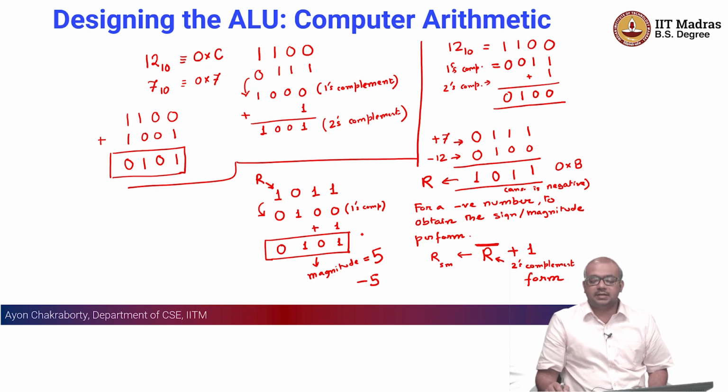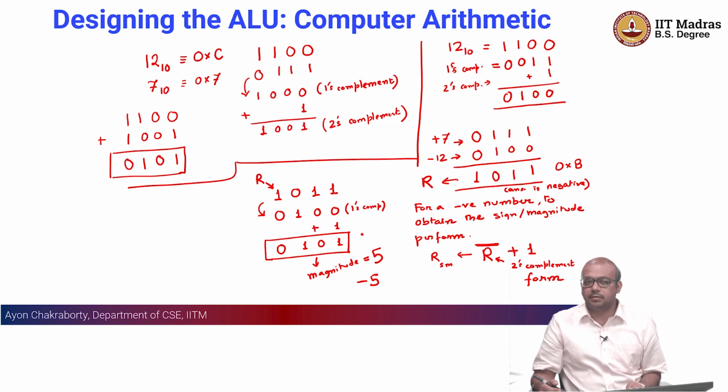Since as a part of this assignment as well as the next assignment for the last 2 weeks, we will be focusing more on the design and implementation of these circuits, it is very important to test a circuit once you develop or implement it. Otherwise, if you have many such circuits developed and you put them together and it does not work, it will be very difficult to debug what exactly went wrong, because this is hardware, you cannot really put printf statements here and there and track the source of the error.